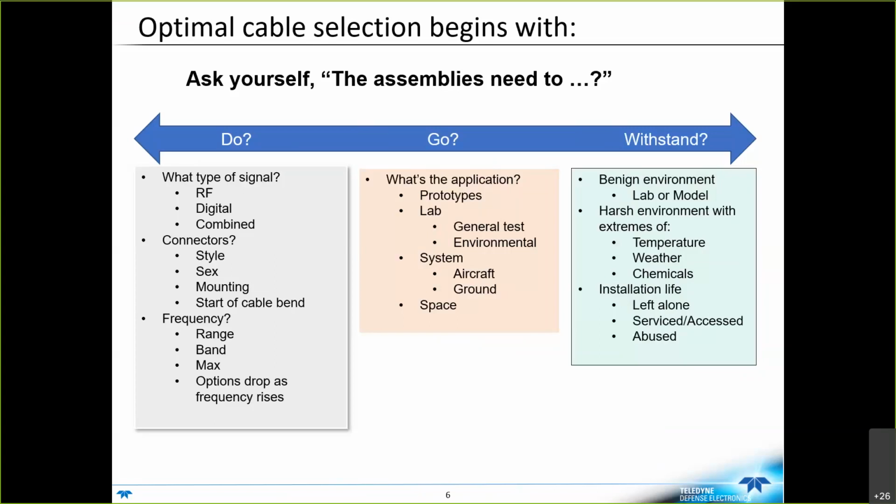Teledyne Storm cables that have been validated as we release them are certified over a temperature range of -55 to +125, meaning we go through all of the validation procedures for thermal shock, temperature ranges, phase stability over temperature. There's a wide array of reports that we can provide that give you how the cable performs over that temperature range. Anything beyond that, now you're getting into some more extremes, which are going to have much bigger effects on the cable. So whether your cable may be cycling over those really wide ranges, or you're just going to get really, really hot, those are important points to talk about fairly early on.